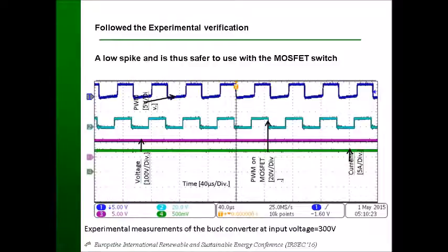So what I did, I measured the output voltage and current, and I looked for the ripple current and ripple voltage at the output, but there is no ripple and the result is acceptable. Then after this procedure and this design, we can implement the control, and we can design the PV array emulator, with which we can test the PV inverter. This is what I have done.